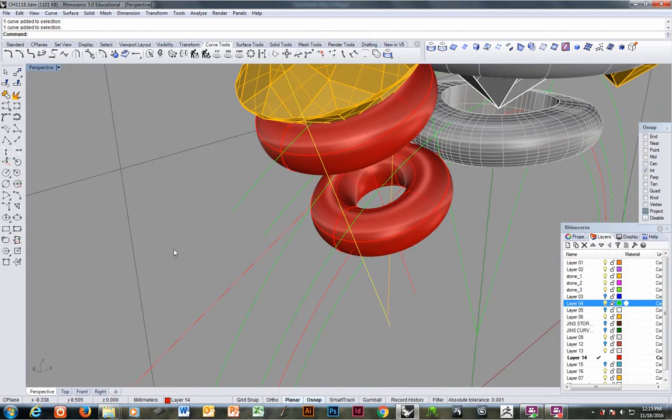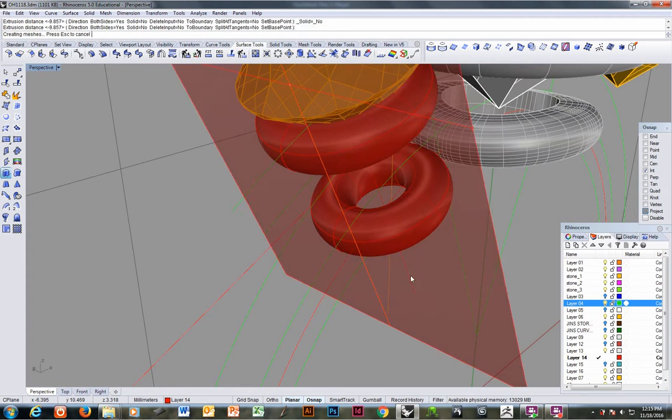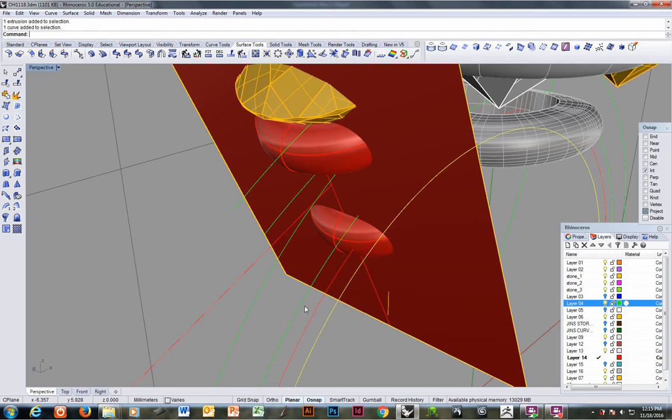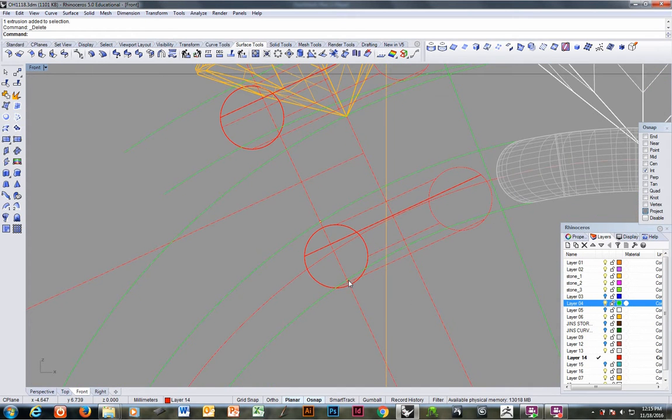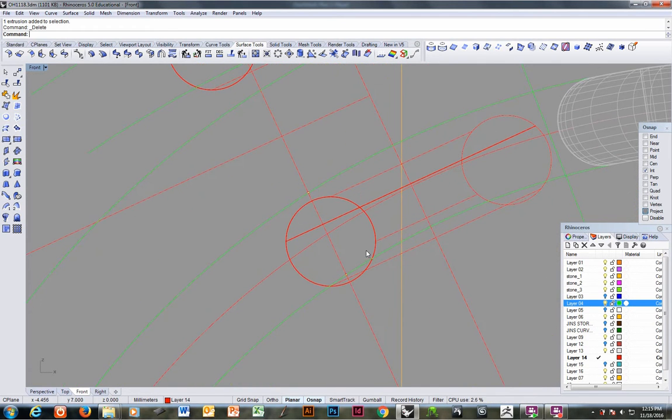Oh, sure, I always have a choice. Surface, extrude. Give me an intersection with those two points, with those two curves. Please. There, thank you. Now I have points. And I'll use those points with the project option so it doesn't move in and out.